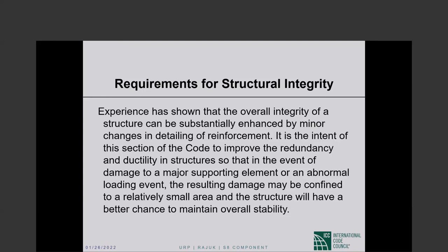But the further away you go from the tension face with these layers, the less effective your reinforcement becomes, right? Tension reinforcement is the most effective when it is close to the tension face. So it will be in your interest to keep the layers as close as possible, not violating that 1 inch gap. There is no upper limit because who would think of putting an upper limit? It is in your interest to keep the layers as close as possible to the tension face.